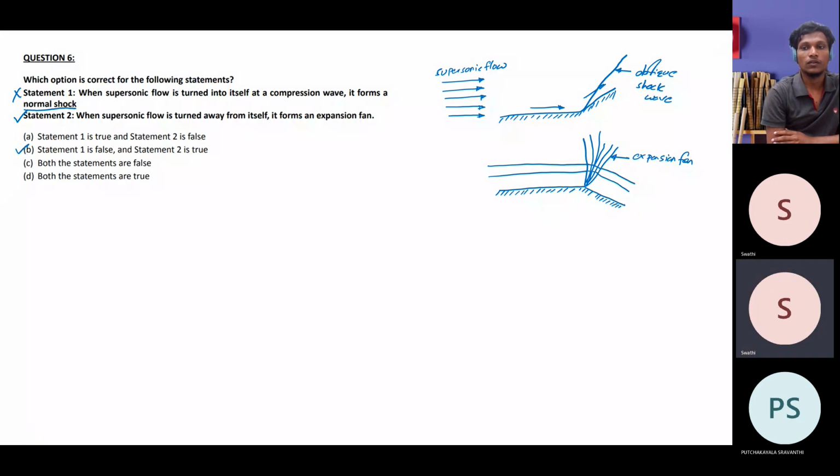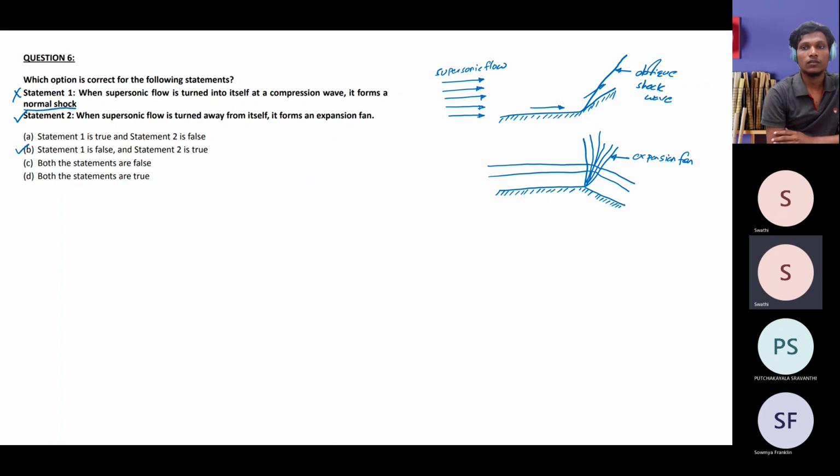If it is supersonic flow, we have expansion fans and shock waves, right? What will be the case if it is a subsonic flow? In the case of subsonic flow, you don't see this kind of behavior, because in subsonic flow the information can travel. The sonic condition is the transonic condition, which is an entirely different theory. We always look at either subsonic or supersonic. In subsonic flow, if the flow is moving away from its path, will an expansion fan be available or not?